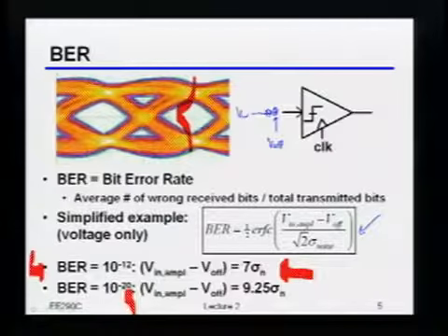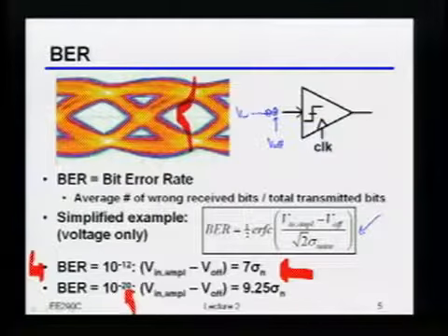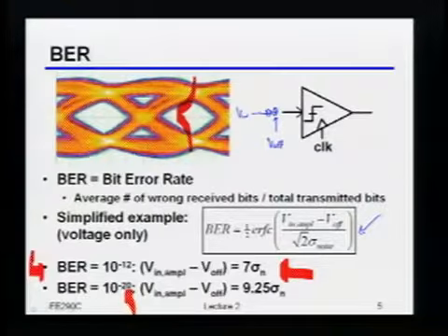You don't. What you do, of course, is you intentionally mess up the receiver, and then see if it's tracking the curve that you expected. Now, actually, I'll be slightly mean, but I think this is true. In computer systems, what they basically did is they shot for this 10 to the minus 20. They turned the thing on. They ran it for an hour. If they didn't see any problems, they said, OK, we're good, right? Because, by the way, in a computer, it's not just one link that you've got there. You've got a lot of links, right? So if I've got 1,000-something links, even this 10 to the minus 20 number starts dropping pretty quickly. But you're absolutely right. Measuring 10 to the minus 20, even with a 10 gigabit per second link, is a lot of seconds, right? So that takes a while.